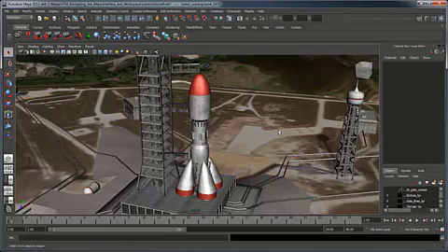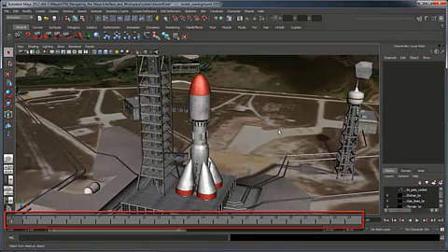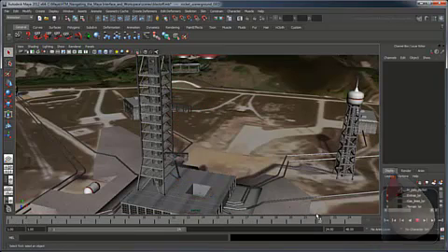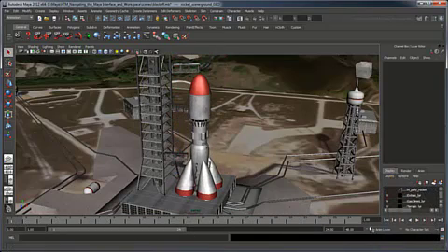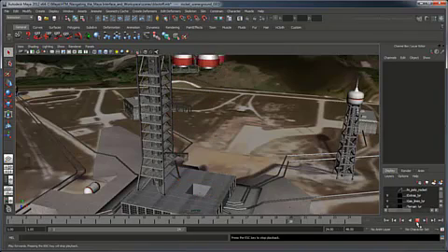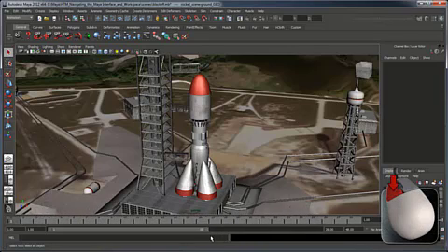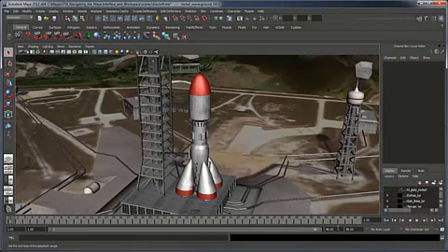The bottom portion of Maya's interface is dedicated to animation and scripting. The time slider allows you to quickly navigate your animation frames by clicking and dragging over it, also known as scrubbing. You can also use the playback controls on the right to play through your animation or step through keyframes. By default, Maya displays 24 animation frames. You can drag the range slider control or use the input boxes to add more time to your animation or display a subset of it.